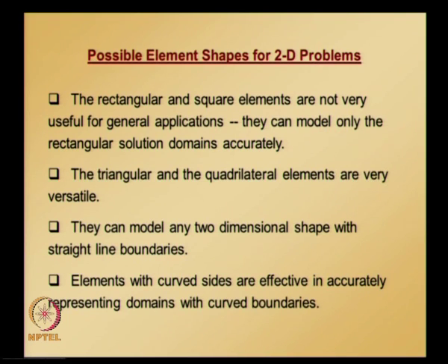And equivalent functional is required if finite element solution is based on Rayleigh-Ritz method. And we also look at how to derive element shape functions for 3 node triangular element. The procedure helps us to understand, or to generalize it later for any noded 2D element. And also we look at the Galerkin criteria for 2 dimensional boundary value problem to derive the element equations.